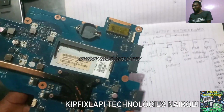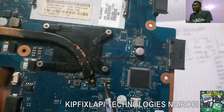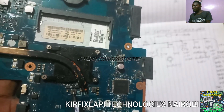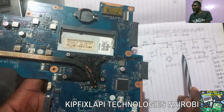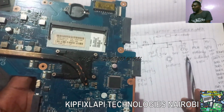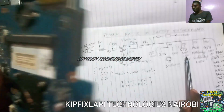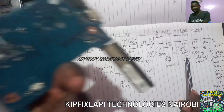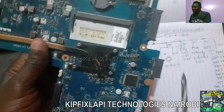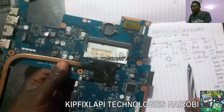Yes, and again here you can see we have very small inductors. These are the power supply for the processor. So maybe this one will be for this power supply. I said we have 1.05. Here still we have another power supply for 1.5 voltage, and of course probably there is another one somewhere, maybe at the back. At the back I am not seeing any. However, I can see there is another one here. So maybe it's for the 0.8 voltage or whichever.